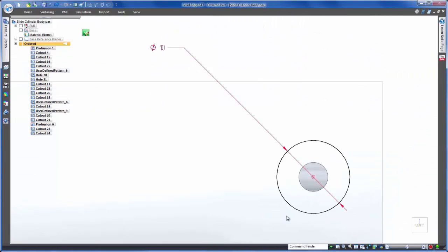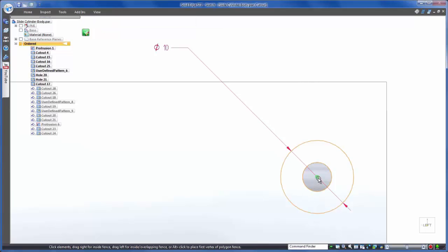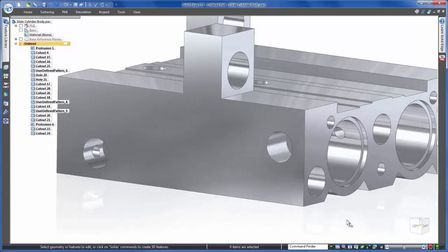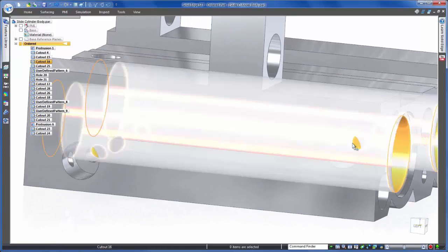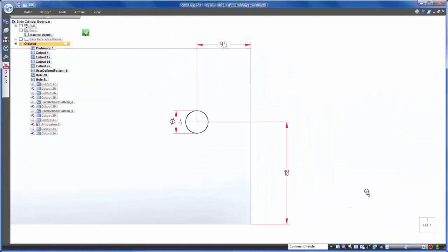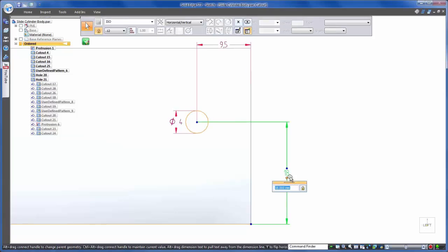Now that we've subtracted 1 millimeter to the front hole, we need to do the same with the top. Repeating the same steps, we notice that this hole is not defined the same way as the previous. This counterbore is modeled as a cut and is concentric to the smaller hole running through the slide cylinders. This sort of frustrating situation is often run into in history-based modeling.